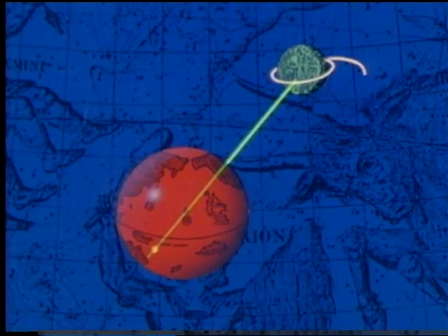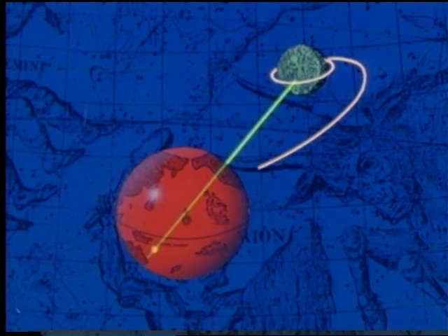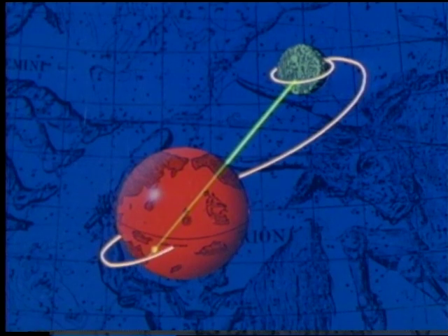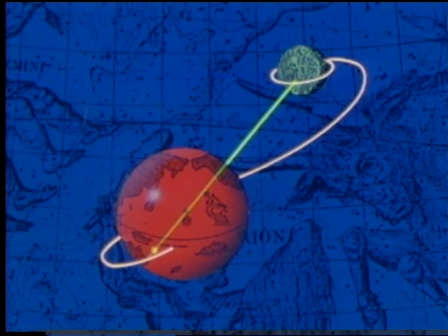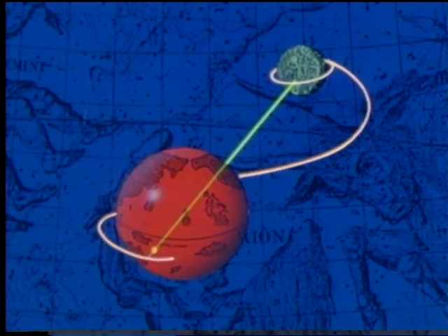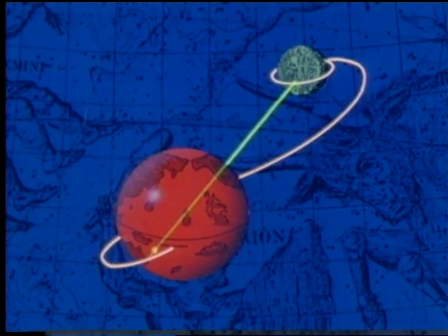The return trajectory begins at the Moon and must pass over the antipode. This means that the plane of the return trajectory must contain the Earth-Moon line. The injection burn to start the lunar spacecraft on its return trip will also fix the plane of the return trajectory. This plane can be rotated around the Earth-Moon line. The limits of this rotation are determined operationally.